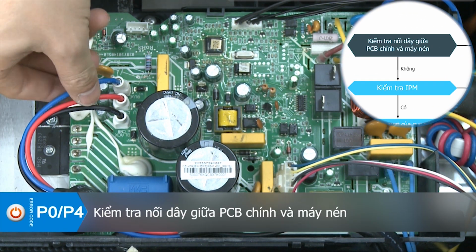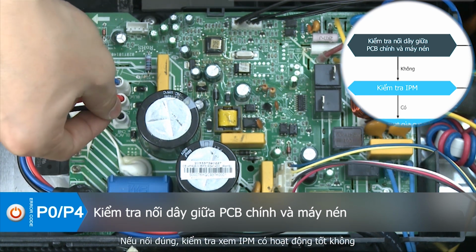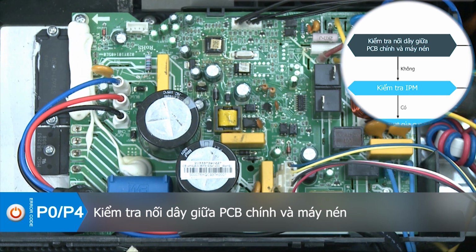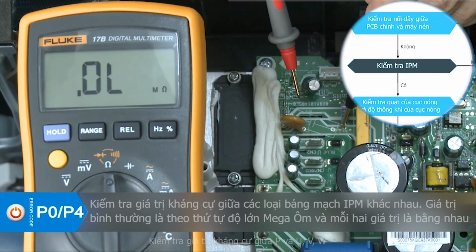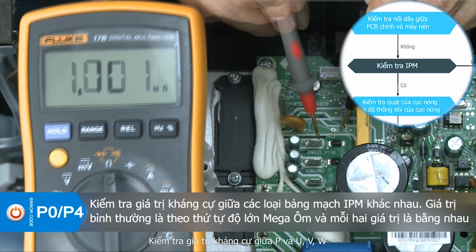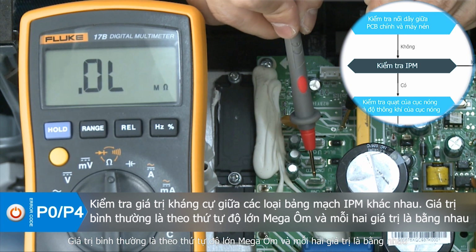Check the wiring between the main PCB and the compressor. If the wiring is correct, check if the IPM is operating well. Check the resistance value between P and U, V, W. The normal value should be in the megohm order of magnitude, and each two values are equal.